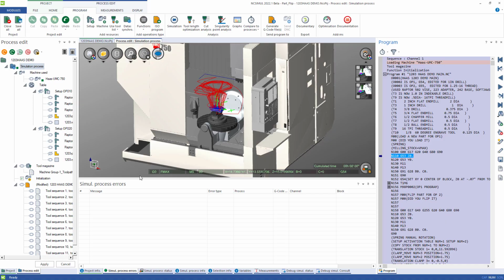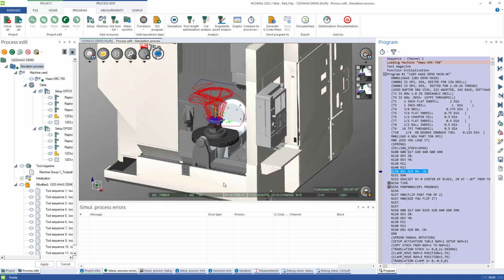And that's why it's always good to kind of go top to bottom in your error messages, because you see by changing that 1, we had a bunch of extra movements that were at that height. So it gets rid of a bunch of extra errors, which you would have seen if it moved a bunch of times out of the envelope. And that's all there is to do to step 1, kind of move top to bottom. And when you're done, like this is, you should see this window blank, and this button down here is green, meaning we can move to step 2.